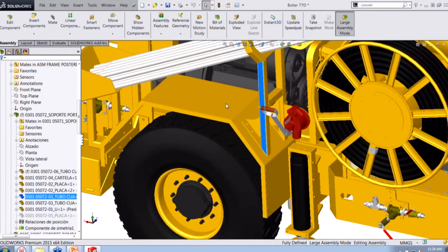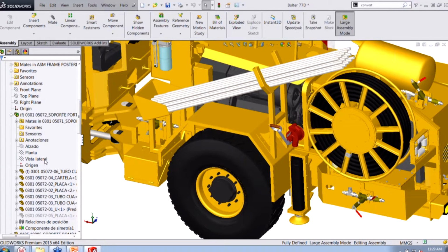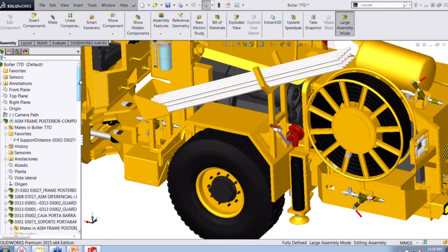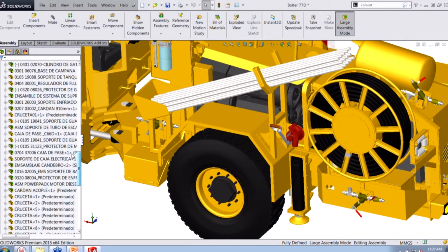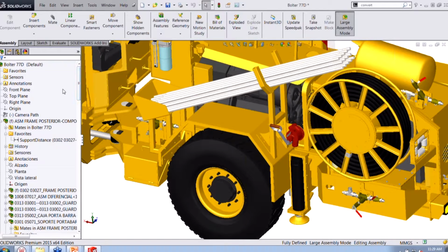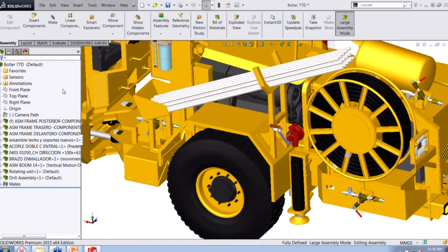Also a little shortcut, let me go ahead and go back. On the left-hand side, you can see how I have my feature manager expanded out, right? An easy way to collapse this, if you want to be able to just see a quick top-level view, is you click in here and press Shift-C. What that'll do is collapse your feature manager for you, okay? So that's Shift-C.